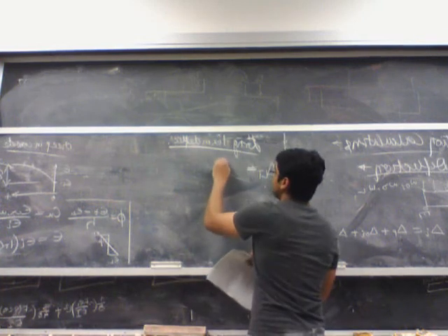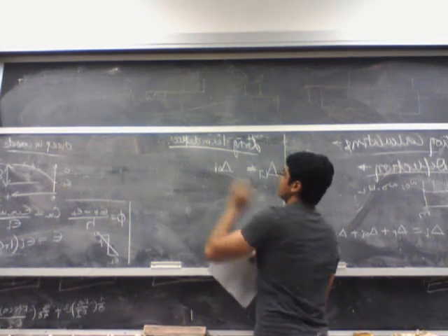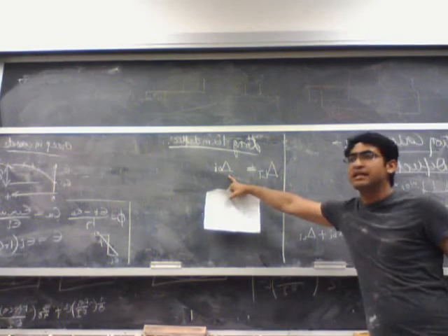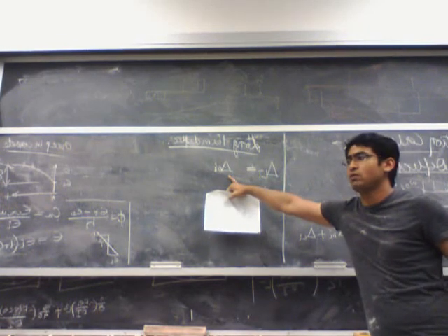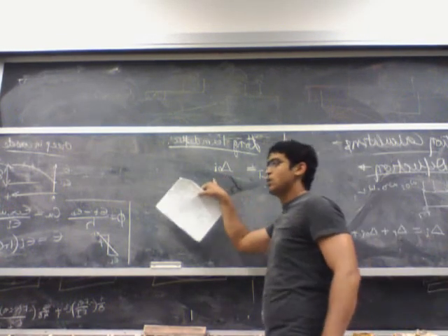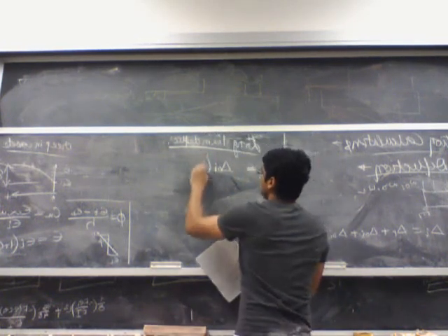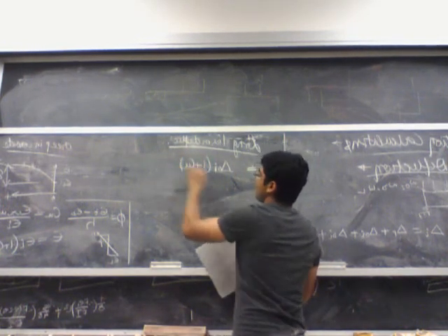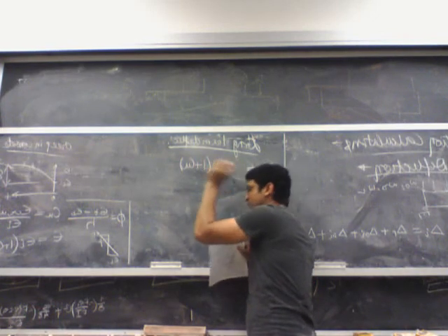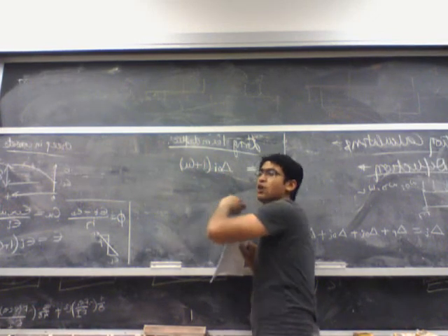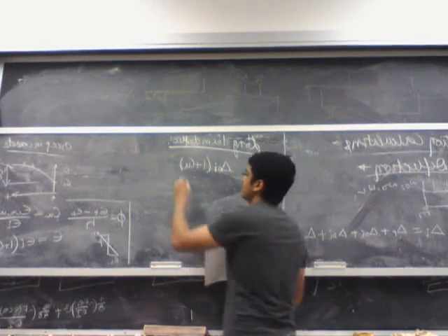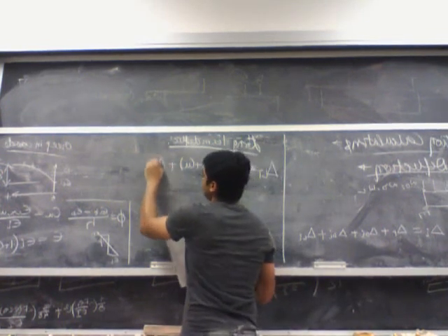So let's start with the dead load. This is the instantaneous deflection due to the dead load. So what is my long-term deflection just due to dead load? It's simply this times 1 plus Cu. Why? Because self weight is a sustained load. It's always applied on the specimen. The same thing with a dead load.